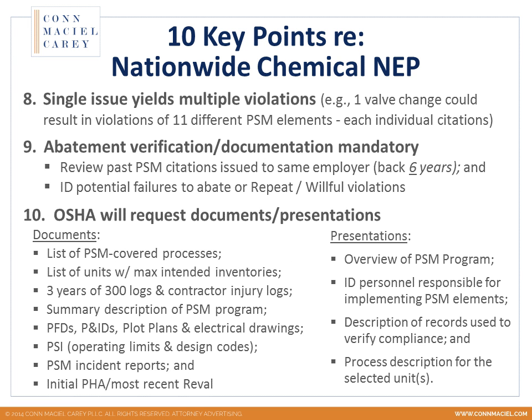The last few items of things you need to know about the chemical NEP, just like the refinery NEP, a single issue yields multiple violations. The same discussion we had before, we're seeing that carried through in the chemical manufacturing facilities as well. Abatement verification and documentation is mandatory. OSHA is looking at past PSM citations issued to the same employer going back 6 years, which is different than the standard for identifying repeat violations.